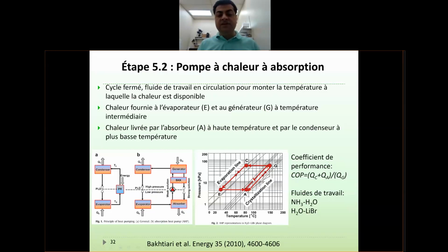But what is this heat exchanger? This solution heat exchanger is just one step that you can add so that some of the heat from the solvent can be exchanged with the solution here, so that the QG that you need to use is going to be less. In order to minimize the QG, you can put a heat exchanger so that you take advantage of the hot, or maybe warm, solvent.